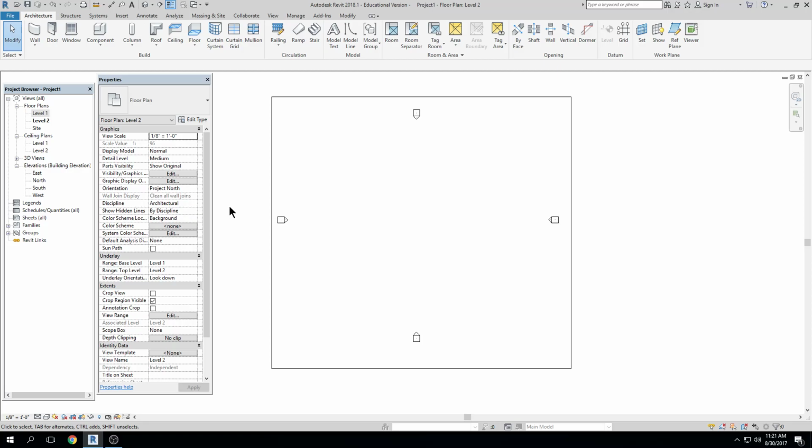And Revit is no different. We have to, number one, initiate the command. We can do that by clicking on an icon or typing a keyboard shortcut. Number two, we need to specify a starting point. We're going to do that by clicking in what I'm just going to call model space, in AutoCAD terms, the drawing board, right? We're going to click in model space here, and then we're going to move our mouse in the direction we want that object to be drawn in, and then we're going to either type a dimension or just click to end the command. All right.